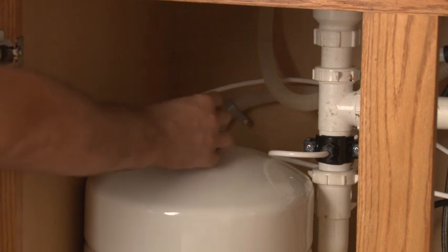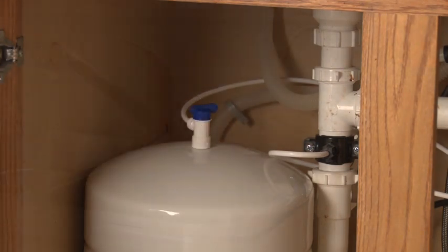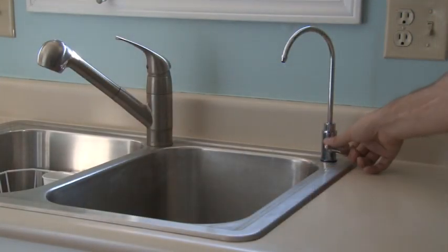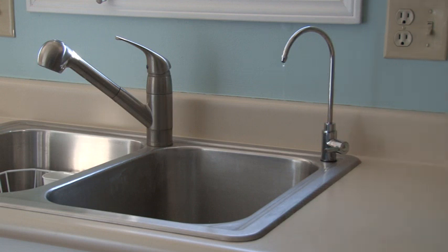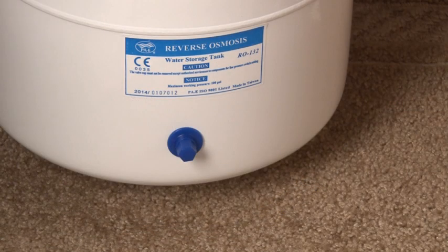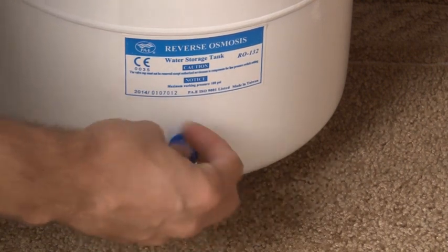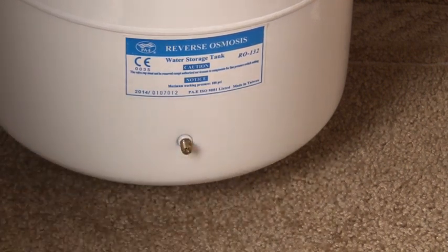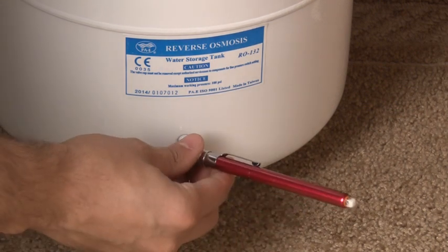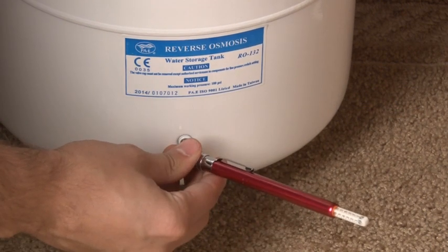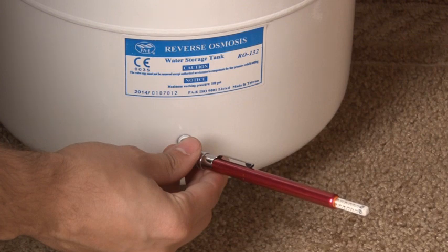If you wish to check the performance of the membrane, you can close the ball valve on the storage tank and check the quality of the water that drips directly from the membrane with the faucet open. Allow at least a quart of water to drip from the faucet before checking the quality. It is recommended that the pre-charge in the storage tank be checked annually. When the storage tank is completely empty, it should have between 5 and 7 pounds of air pressure.